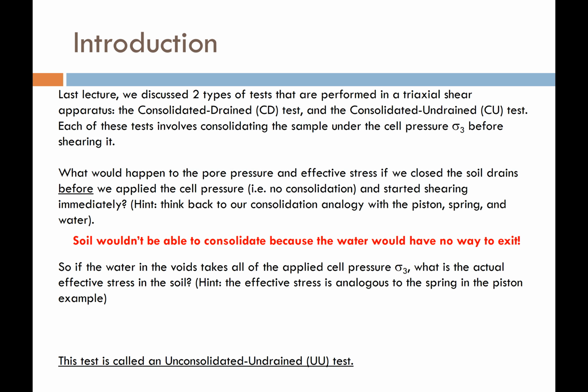So as a result, the soil can't consolidate because there's no way for the water to exit the soil. So if the water in the voids takes all of the cell pressure, and in addition to that, takes all of the pressure from the loading ram of the triaxial device, we might ask the question, what is the actual effective stress in the soil?